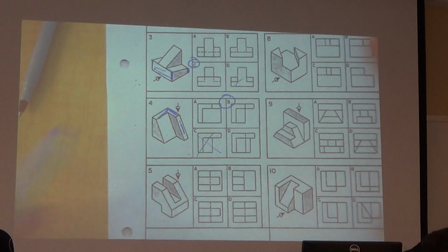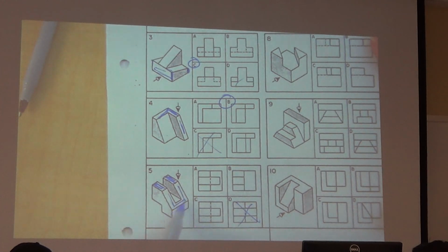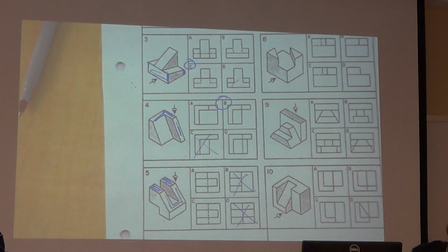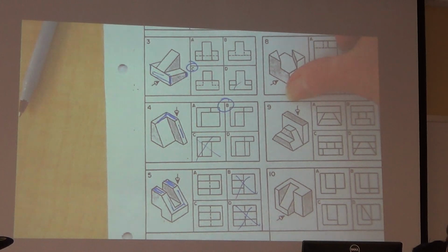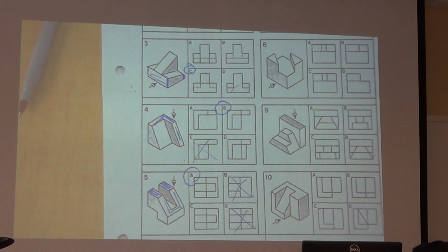So Ben, you're on. So we're looking at 5. I'm looking down horizontally. I see these two here. I see again, even though it's inclined, it's just going to be a plane. So this one can't be, because I'm going to see this edge. This one can't be it. It's got to be one of these two. And then underneath, there's this edge that I can't see, so it's going to be governed by a hidden line. What's the difference? I have to put my glasses on to see the difference between these. Oh, okay, I see. This is a visible line and this is a hidden line. Ben, which one is it? A.